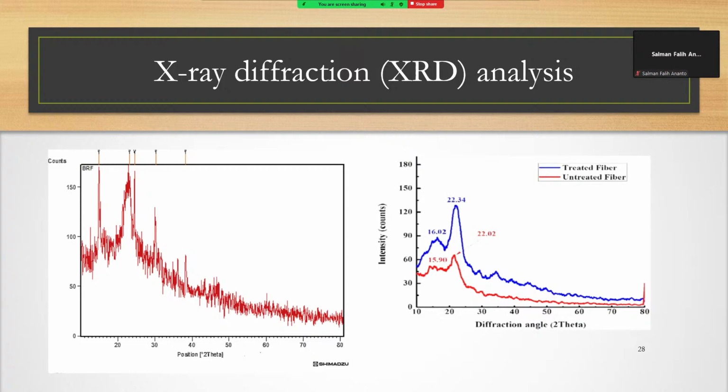The next is Fourier transform infrared spectrometry, that is FTIR. FTIR is considered a non-destructive analysis that can provide both quantitative and qualitative details of natural fibers. An infrared absorption spectrum is obtained from the chemical composition of natural fibers, and the FTIR spectrum obtained from natural fibers is principally absorbed in the range of 400 to 4000 inverse centimeters, and based on the peak position and its corresponding